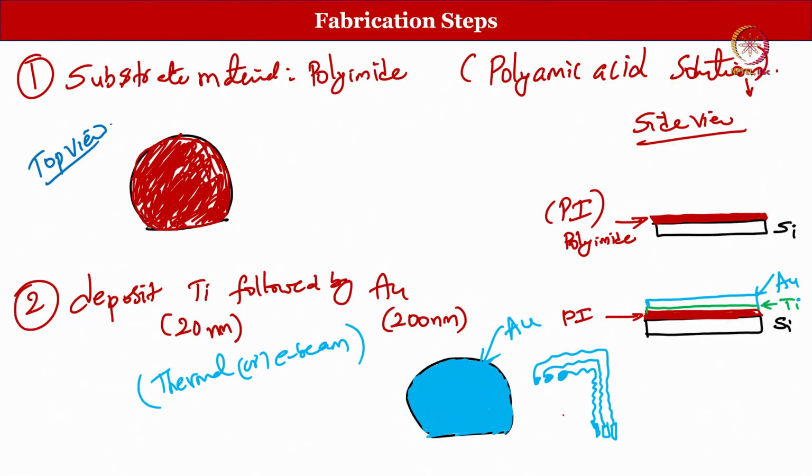So, the third step is going to be lithography. I will quickly explain what lithography is. I think the professor of this lecture has already explained earlier how lithography works. What do you do? You need to have a mask, right? You need to have a mask, then photoresist, you spin coat the photoresist,